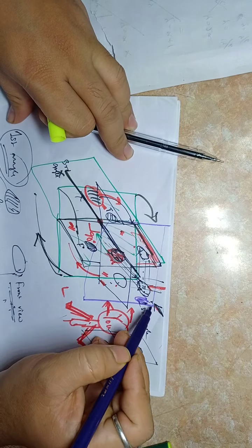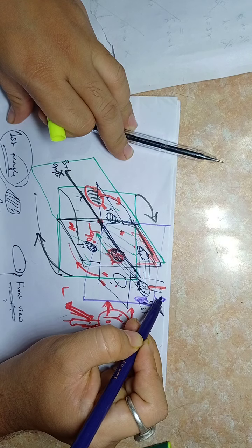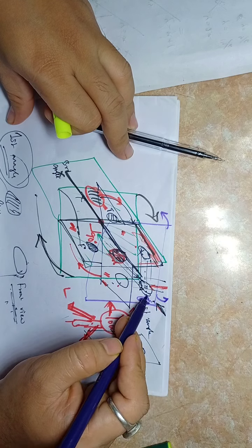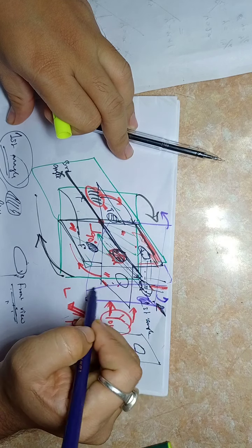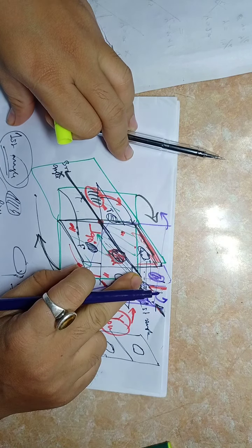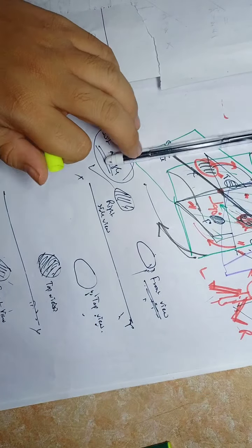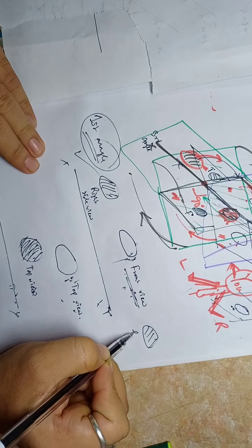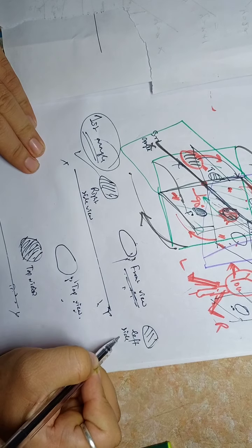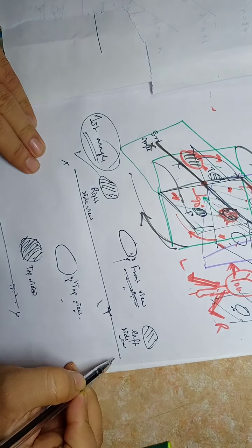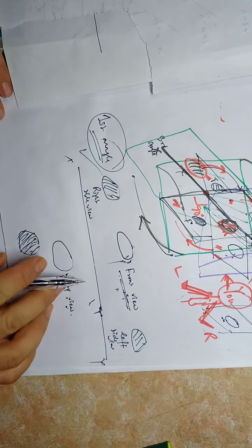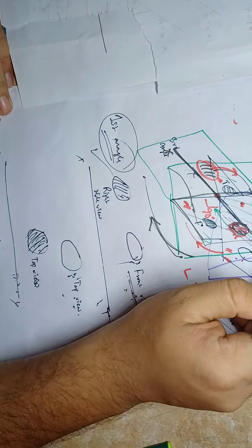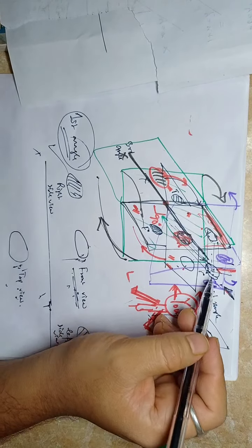Similarly, again you have to rotate this plane 90 degrees to merge with the vertical plane, and this view will go here. So your right side view is here, and the left side view will be here. Everything above the xy line. So this is the complete projection of the object, that is orthographic projection.